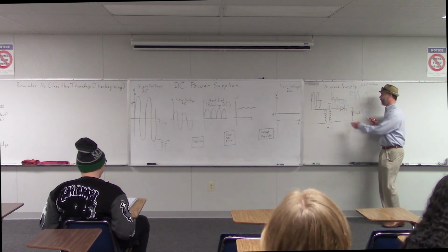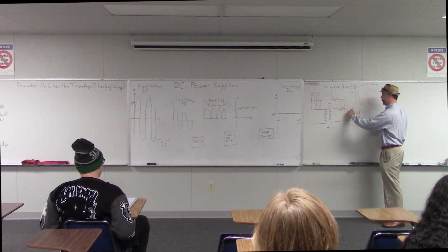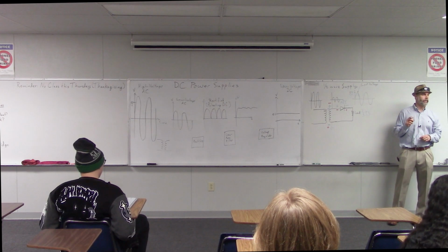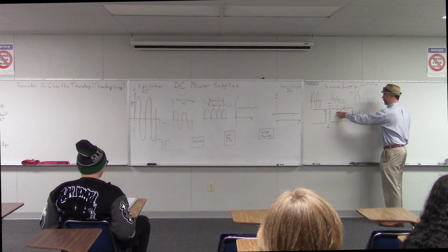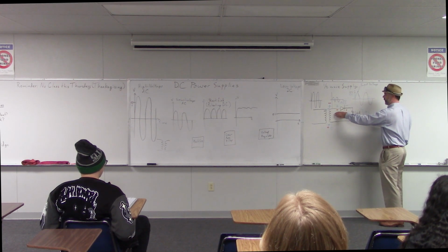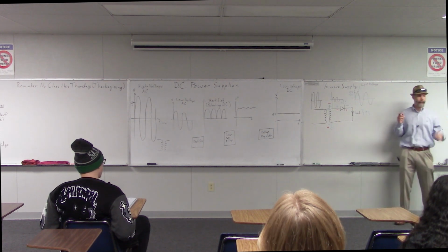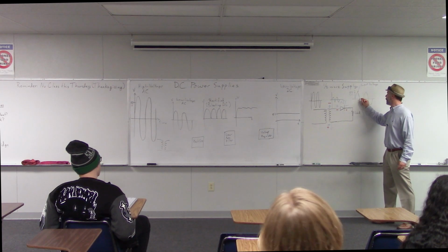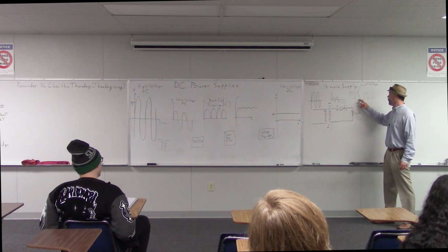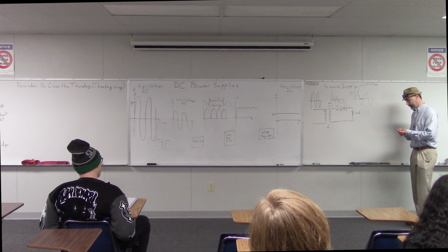So now all of the voltage from the supply is across the diode. So how much is left across our load? No, all of the voltage is across our diode. Remember, when it's reverse biased, all of the voltage is there. So how much would be across the load? 0, exactly, 0. So if we looked at our signal across our load here, when the input goes negative, the signal across the load is just 0 volts. Okay?